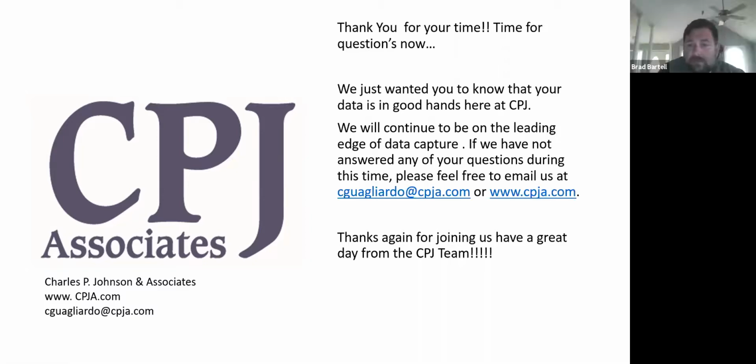I do have a question from Spencer on my answer. He just asked what we use to obtain the measurements from the photos we upload, and that's Pix4D. I mean, that's pretty open to everybody, but it's basically, I'll say this again, however good your survey quality control is. So if you go out there and set control that's only good to 5/10, your photo is only going to be good to 5/10 in there. So that's the main thing on that.